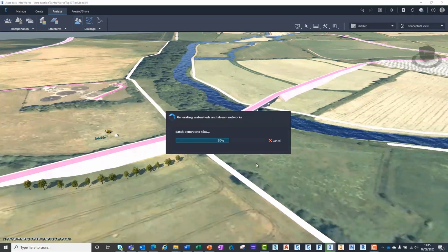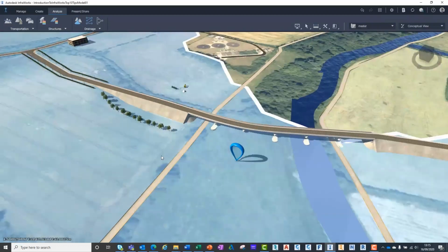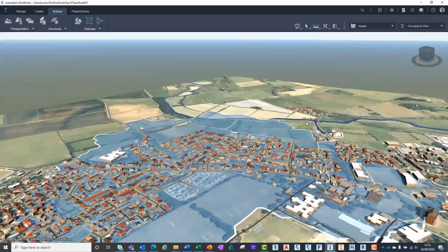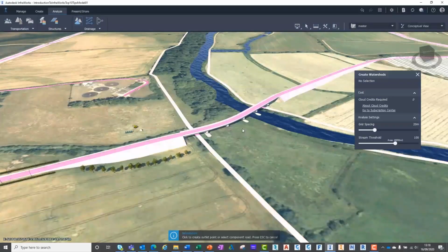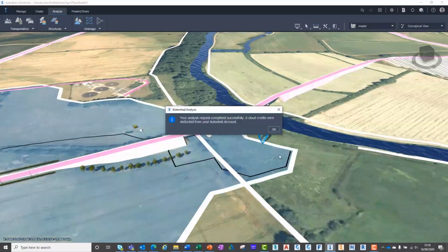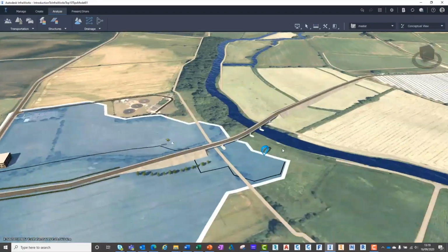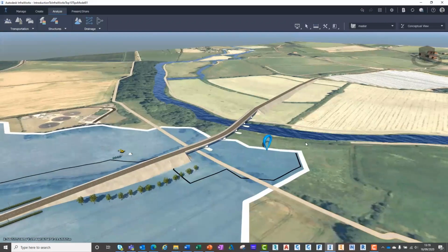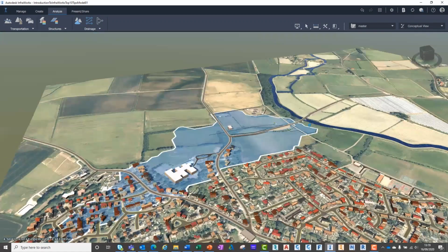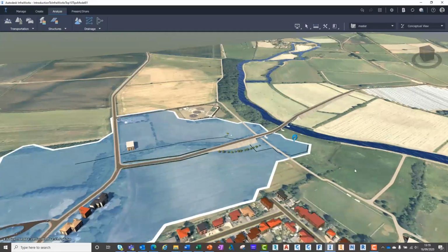InfraWorks then adds a map of where flooding would occur due to the topographic elevations and input parameters. As you can see, we may have gone slightly over the top with our inputs, so let's try reducing the stream threshold. Now we have reduced our model inputs, we can see that the area of flooding has decreased dramatically since our previous run. This tool goes beyond construction geometry and demonstrates InfraWorks' versatility and discipline crossovers to more geographical and GIS specialisms.